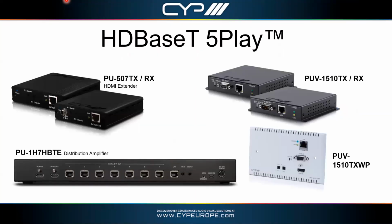Typical examples of that would be models like you see here. So on the left-hand side, you've got the PU507 TX and RX, a straightforward full HDBaseT point-to-point kit, HDMI in, HDBaseT up to 100 meters, and then HDMI out at the receiver end with IR back and forth.